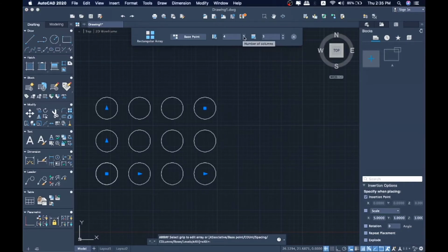From this option, you can change it to 5 or as you want. This option may look a little bit different on your machine than on mine. Okay, I guess that won't be a bigger issue. You can figure it out. Now there are some options here. The first one is spacing, the row spacing and the column spacing. So here the column spacing is from this point to this point. You can change it. This is by default 3.8318 in my case.